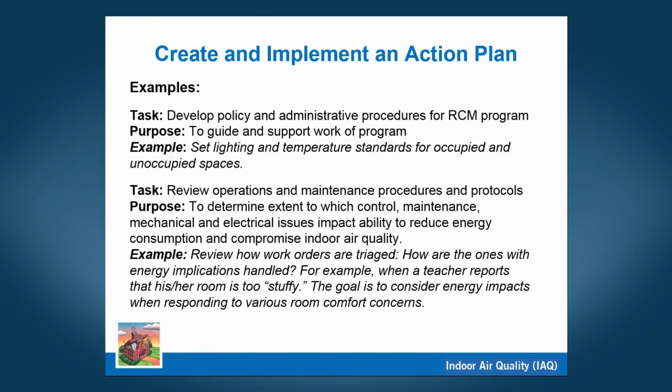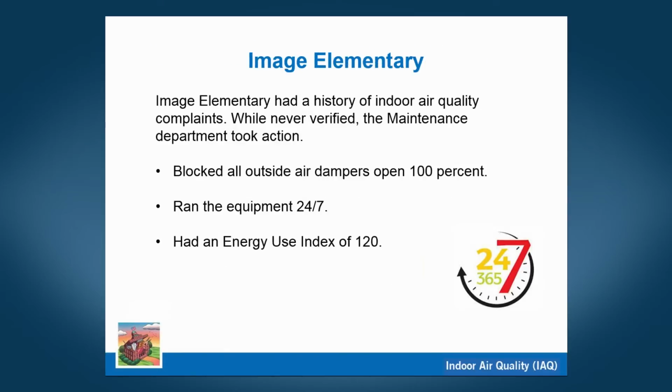Down at the bottom, one that was important to us, review how work orders are triaged, because back to that mutually exclusive reference, it's not uncommon for maintenance people to simply want to make the complaint go away and not think about the energy implications. Or the other side of that is we have an energy saving culture, and it might be easy to not disregard, but to minimize the indoor air quality concerns when making a maintenance response.